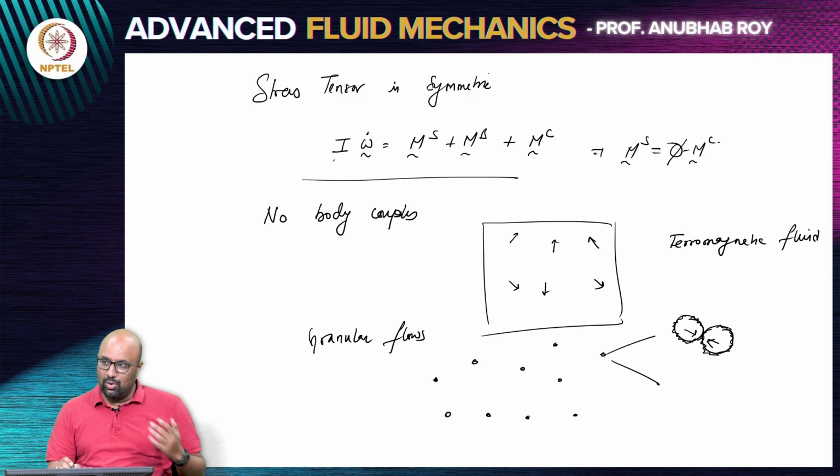In the duration of the course, we are not going to consider problems where the stress tensor will be anything but symmetric. This is the only time we are mentioning this, and after this it is taken for granted. But it is important to know why it is symmetric and what assumption we made, because it's not a very exotic problem where this assumption breaks down. There are going to be scenarios where it will break down, so it is important to understand what leads to the symmetry of the stress tensor. This is not specific to fluids; it's specific to any material that deforms, where you are defining the concept of stress tensor. So now we have the tool set up.